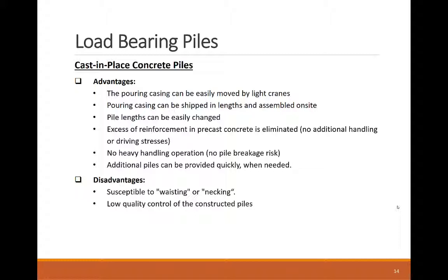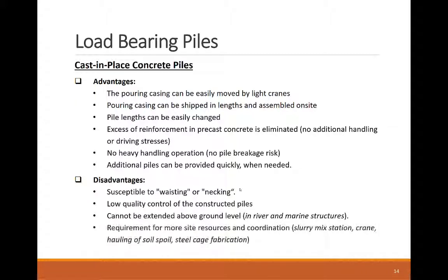Cast-in-place piles are not effective in marine construction, as they cannot extend beyond the soil surface, because soil basically acts as the formwork here. These piles can still be used in marine construction, but they require expensive cofferdams.